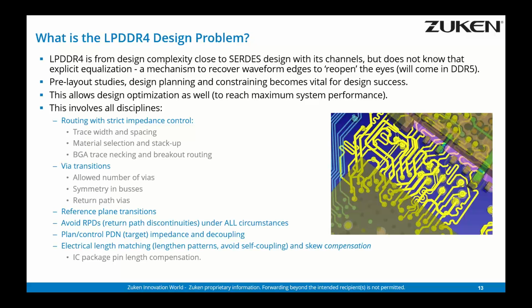So we have different steps which have to be addressed. Routing is more complicated as we have these tiny micro BGAs. We have more complex rules. We have breakout situations where we have different impedance levels from the memory controller to the receiving device. We have required trace width changes. We have very tiny trace widths. I recently supported a customer in a low power DDR4 project implementing 75 microns. So you have to discuss with your PCB manufacturer whether they can implement such technology.